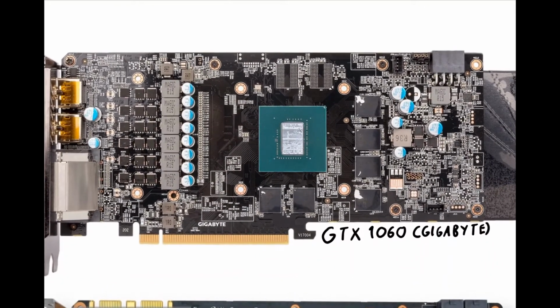So first we have the GTX 1060 from Gigabyte, and the first thing I look for is always the VCORE VRM. Here we have 1, 2, 3, 4, 5, 6 inductors. We do not see any doublers. They could be on the back, but GTX 1060s draw about 120 watts, I would say. Doubling 3 phases doesn't really make sense to me. So the lowest phase count you would double is generally a 4 phase. It does happen that 3 phases get doubled, but I don't think I have seen it on graphics cards yet. I think I have only seen it on certain motherboards.